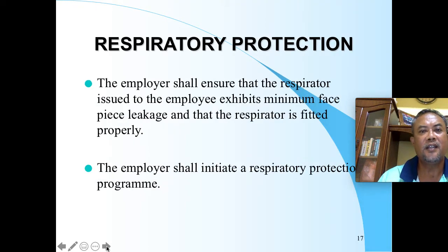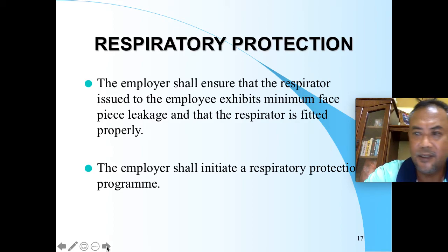The employee shall ensure that the respirator issued to the employee exhibits minimum face piece leakage, and that the respirator is fitted properly. So every respirator has a size, kan? It must be fitted to the individual. Some of the workers are large size, small size, so it must be fitted.